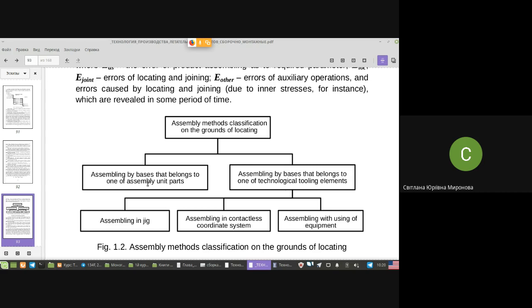Even if you need this surface, normally it is represented with some linear locators, with some fixing arms. So we have techniques which mostly work with contours in a jig, not with the whole surface. The exclusion is work with composite materials, when you need not only to locate something but also to clamp layers to a surface, the whole surface.